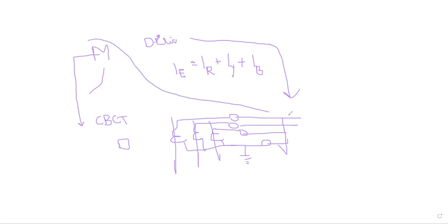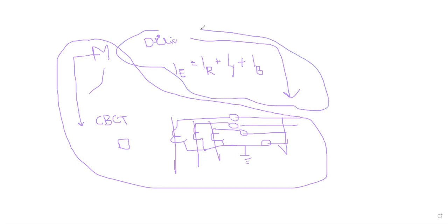In the measured case of the earthing system, the directional overcurrent relay is simple, as we did before, considering the V reference and I reference. But in the case of derived, what is to be done? We consider the polarizing axis, comparing the voltages of the other healthy phases to the current of the affected phase. Here we consider zero phase sequence polarization, where zero phase sequence current and zero phase sequence voltage are considered. Otherwise, negative phase sequence voltage or negative phase sequence current will be considered.